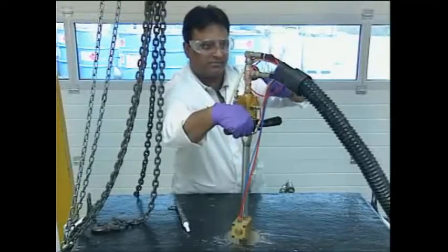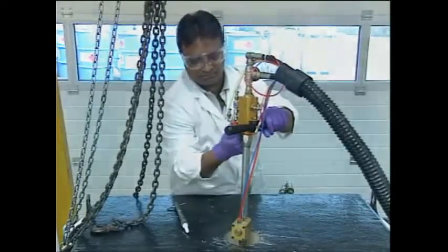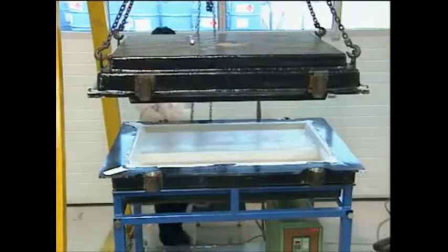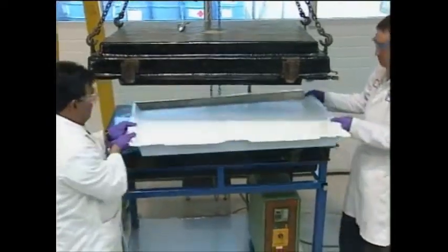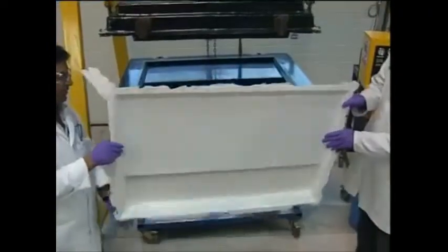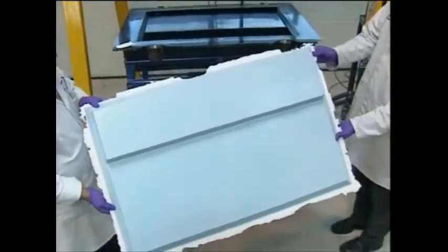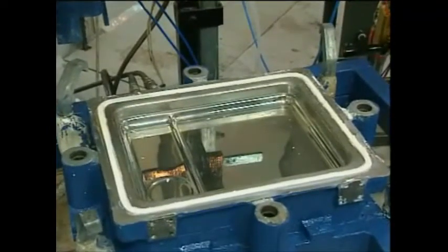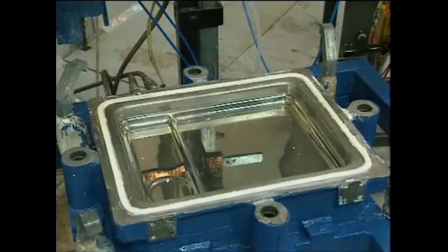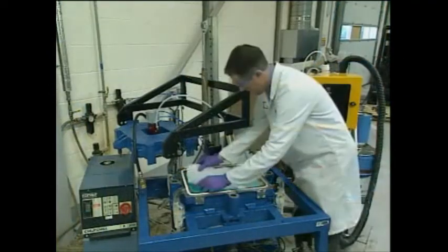Once injection has been completed, the injection head is removed, a stopper is placed in the injection hole, and the machine flushed with solvent. Once the resin has cured, the mold is opened and lifted to allow demolding. The heated tooling allows quicker curing of the resin, and so quicker cycle times are achievable when compared with ambient temperature processes. RTM can use metal molds such as nickel shell, aluminium, or steel for maximum durability and improved surface finish. However, the principles of the mold design and the process remain the same.